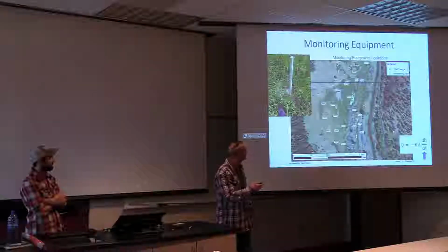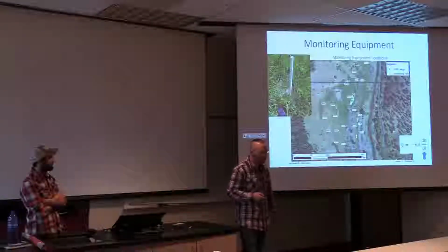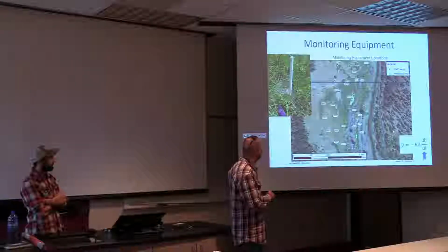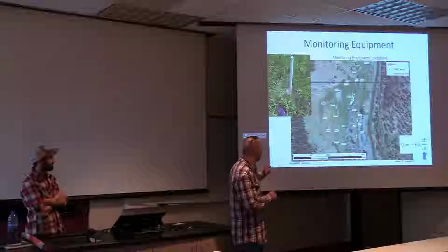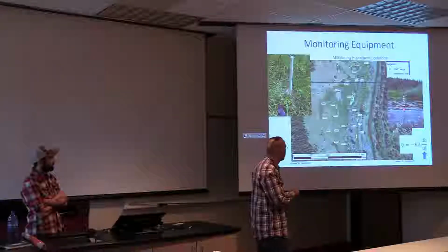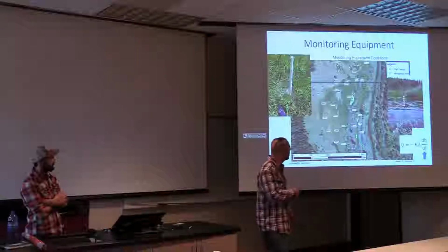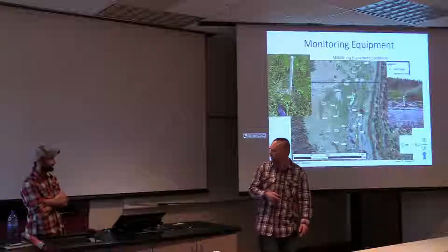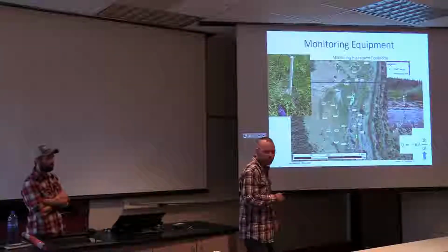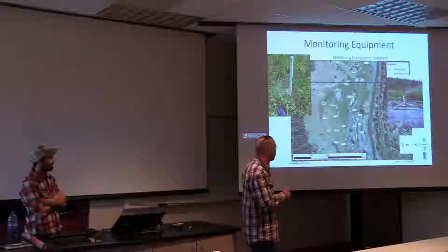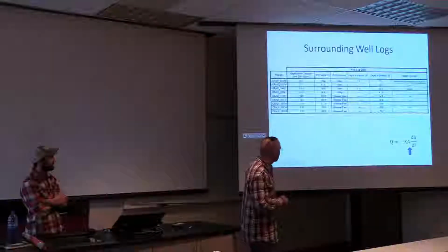Okay, advance. There's a monitoring well. They were hand augered or dug with a post hole digger. That one happens to have an SC meter measuring it. And those are the staff gauges that John made to install. And then all of these have been surveyed in. I think you had a slide in your last presentation of that. So we can get actual elevations of water levels.